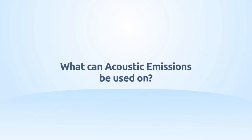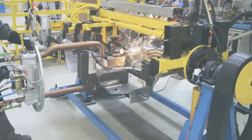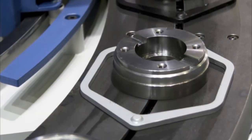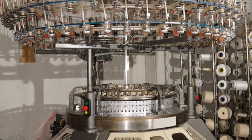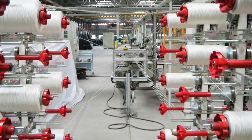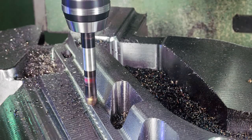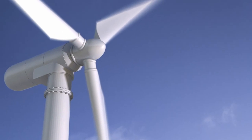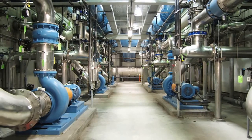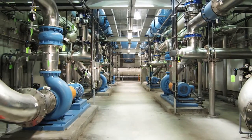What can acoustic emissions be used on? Kittiwake Holroyd's acoustic emissions instruments can be used on most rotating machinery, including pumps, motors, gearboxes and bearings. The MHC Memo Pro is very versatile in the range of operating equipment speeds that it will work with. It has two modes that can be used. Standard mode works for speeds greater than 35 RPM. Super slow mode works for speeds between a quarter to 60 RPM.